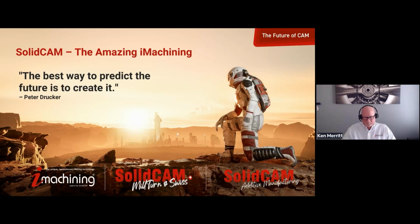Our last question actually kind of relates to that. So what is the difference between 1 and 8 on the level slider? It's the level of performance. What we do is from level 1 to level 5, the cutting edge velocity, the chip thickness, and the minimum and maximum cutting angles are elevating from 1 to 2, 2 to 3, 3 to 4, 4 to 5.